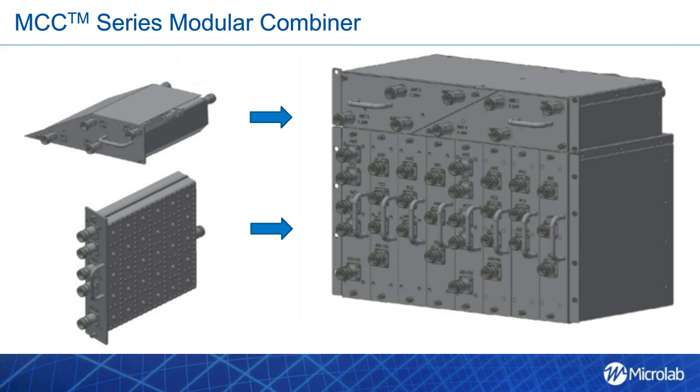It has been designed to provide up to 4 operator SISO configuration for 2 sectors, or 4 operators with 2x2 MIMO in 1 sector, or 2 operators with 4x4 MIMO in 1 sector, or other custom configurations in between. The benefit is that the plug-and-play chassis can be easily upgraded for future requirements, alleviating some of the unknowns and initial costs when the number of carriers joining or site upgrades are undefined.